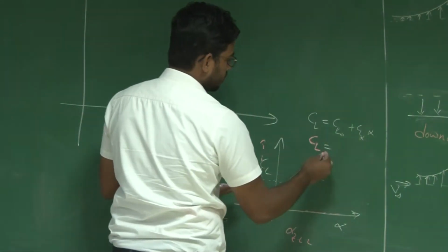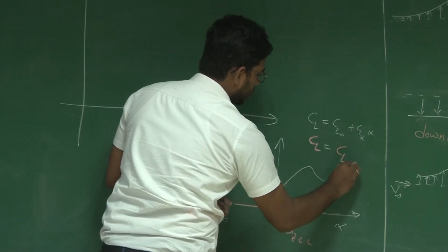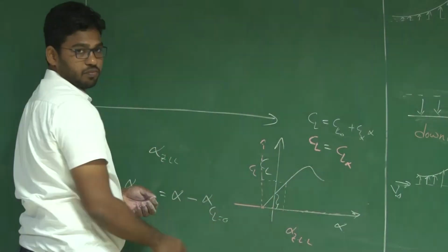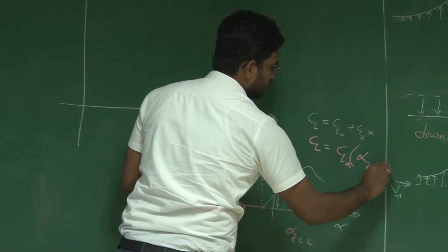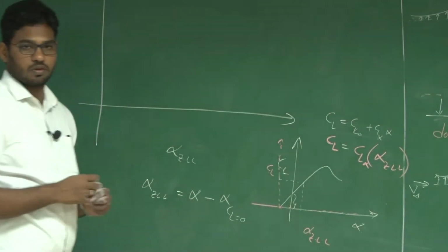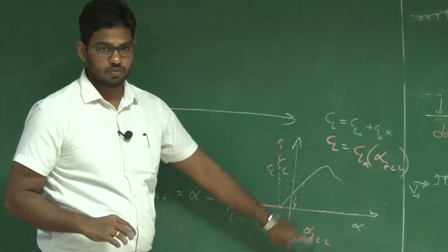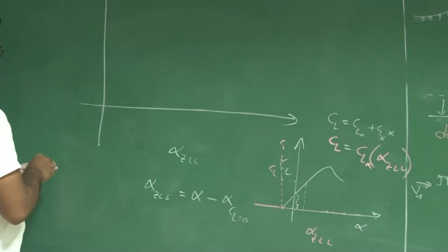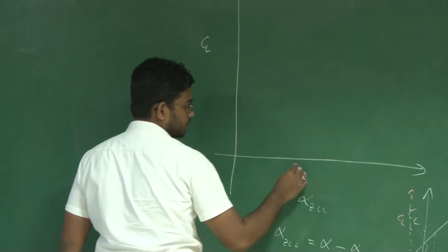So according to this, what you have is CL alpha. The slope still remains the same, only the definition of alpha changes here, with respect to the zero lift line. Now consider a case where we are defining this lift with respect to the zero lift line.